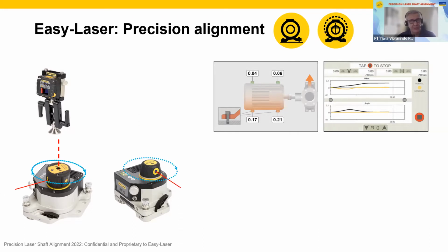While you are starting up the machine into the operating stage, you basically monitor permanent and live the X and Y deviation, so the parallelity and the angularity of the machine parts to each other. And this is used then as an offset to be applied to the initial alignment on a machine that has a cold condition, so that when it is operating or warm up to operation level, it is aligned accordingly to the tolerance and reference.